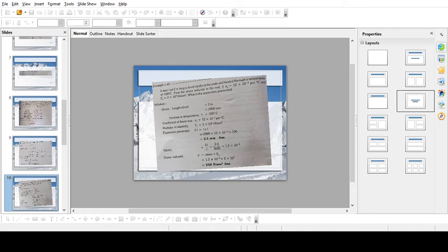So sigma S by 2 plus sigma C by 1.2 should be equal to 200 into 18 minus 12, that is T into alpha C minus alpha S. So 1.2 into sigma S plus 2 into sigma C is equal to 2.4 into 200 into 10 to the power of minus 1 into 6.